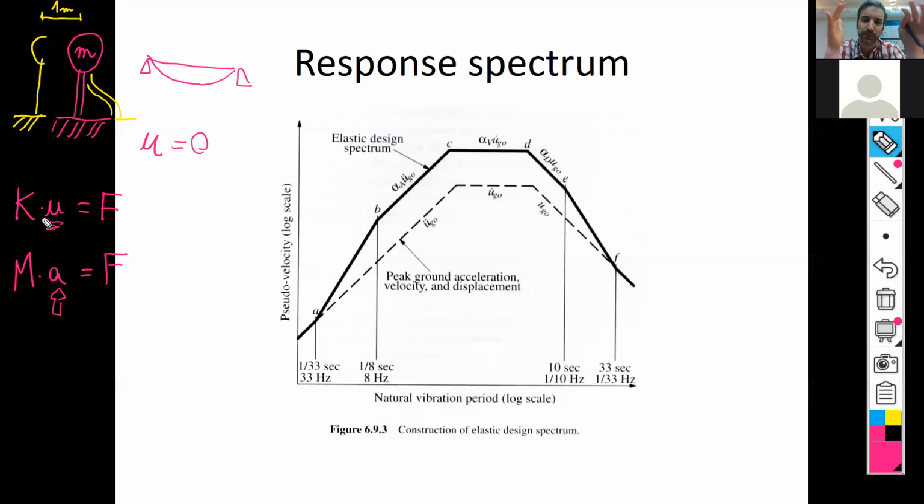Okay, so displacement is always a relative term. It's always when we're talking about one part of the structure in relation to the other part of the structure. And that's what creates bending moments, that's what creates normal forces, that's what creates stresses. While acceleration is an absolute quantity, okay? It makes perfect sense to talk about the acceleration of one point.